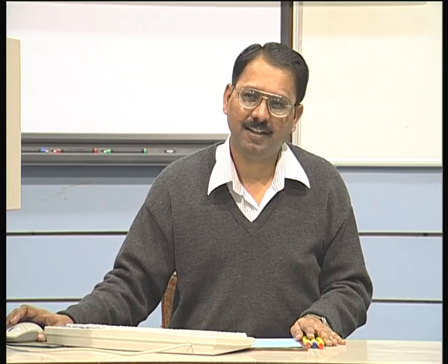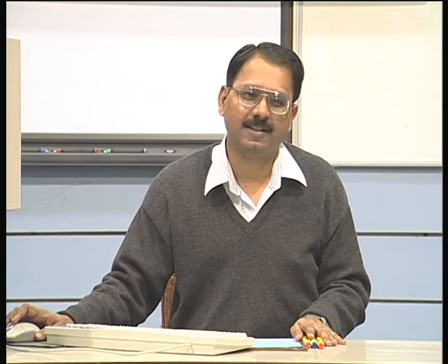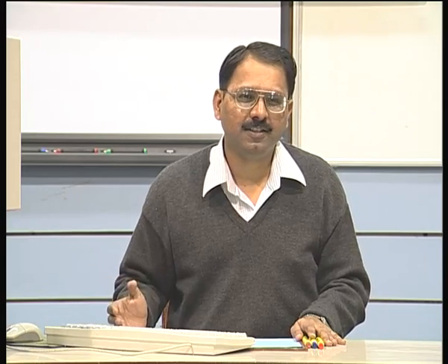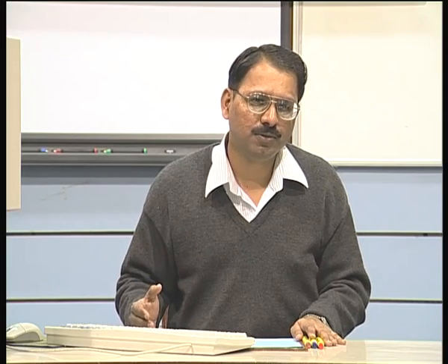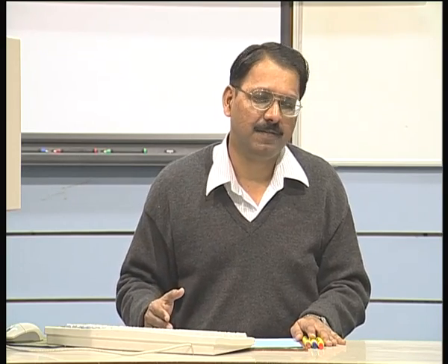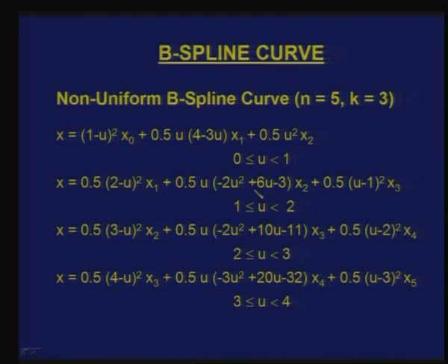Like when I code it as a program, I have to have different cases. If u is equal to 0 to 1, then a particular equation is used. If u is equal to 1 to 2, then I have another equation which is defining it. Now, these equations are derived in such a manner that you do not have to worry about the continuity, it is a part of the definition. So, the slope continuity will be automatically met if I go through this kind of a definition.